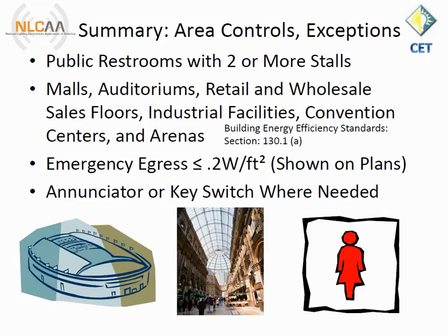Remember, if you get stuck, you can use a key switch or a lock box to make sure that the readily accessible control is not actually used by unauthorized persons if you've been forced to put it into a place where that would render the non-residential function area unsafe.